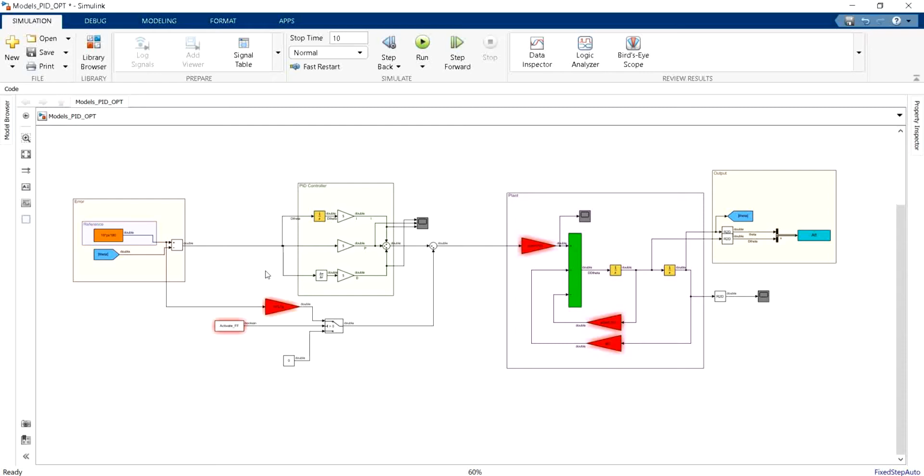When it comes to evaluating or optimizing a controller, we must also define the criteria or the aspects that we are using in order to evaluate the performance of the controller. And in fact, we can define analytically these two aspects via what we call a cost function. And usually when we want to optimize a controller, after defining the aspects that we want to consider when optimizing a system performance, we have to minimize this cost function for this particular controller.